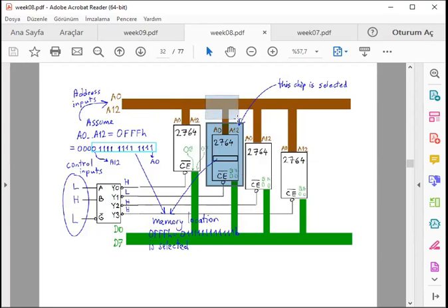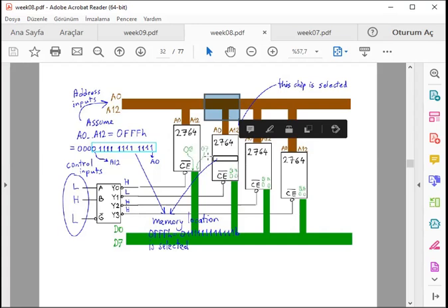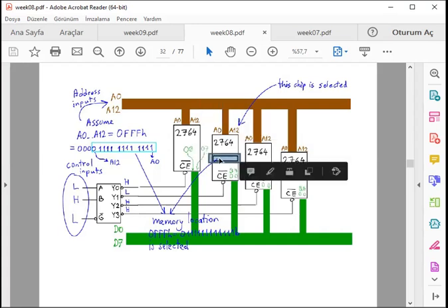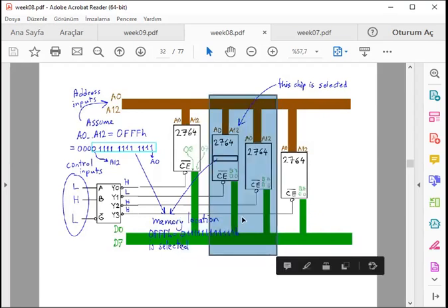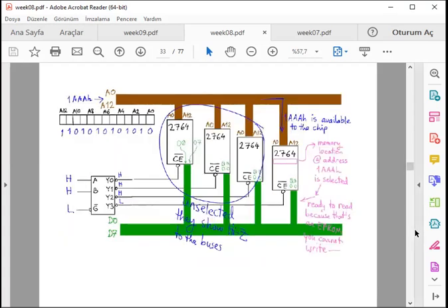According to the address information in the brown, only one of the registers can be selected, and its contents are fed to the output or data bus, which is green. So the importance of 3-state can be seen. If we select 2 chips at a time, their information conflict will make the data bus problematic.